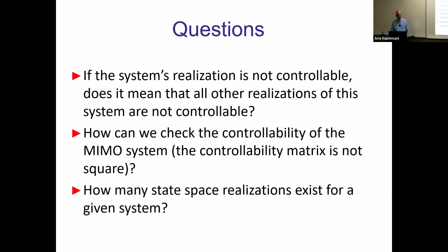So system could be designed as controllable. If the controller is more important to you, to design the controller, you can make the system controllable with a specific realization. But cancellation of poles and zeros will not disappear anywhere, right? So it must then be non-observable, which means that you will need to measure all of your states, which sometimes is possible, sometimes not. And same thing with observability.